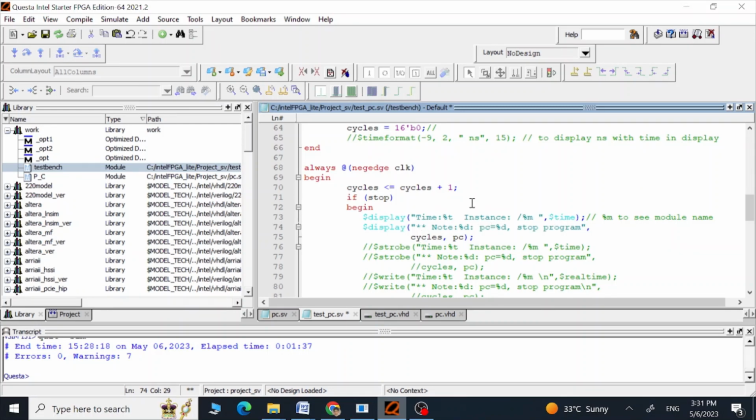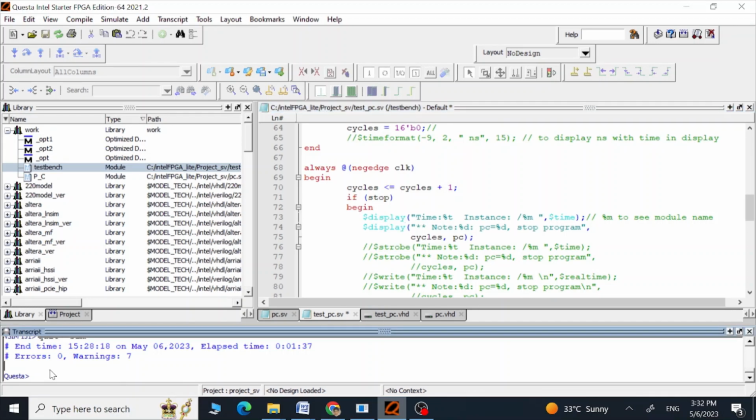And this first %d is going to give us our number of cycles here. The second %d is going to give us the PC inside this display function. So this display function is one of those functions which we can use to display values or our signals onto the console window, wires or tags, whatever there are in the case of Verilog.